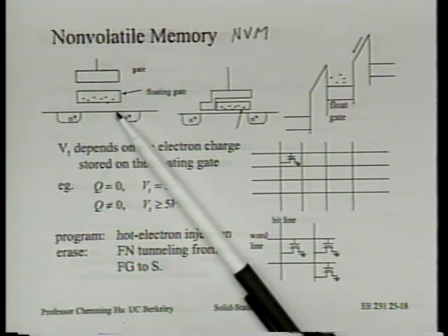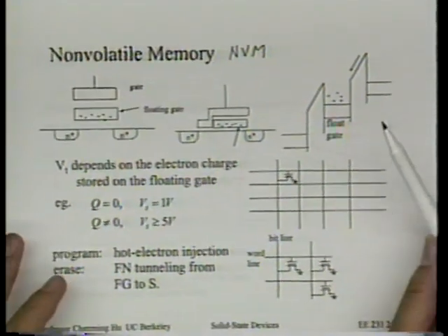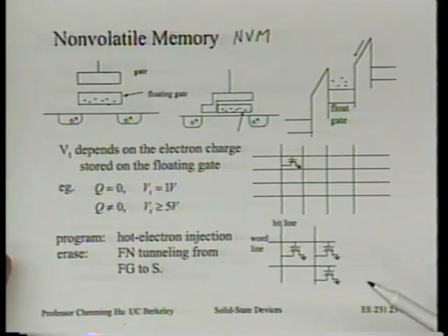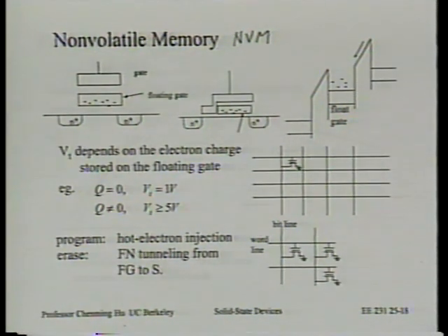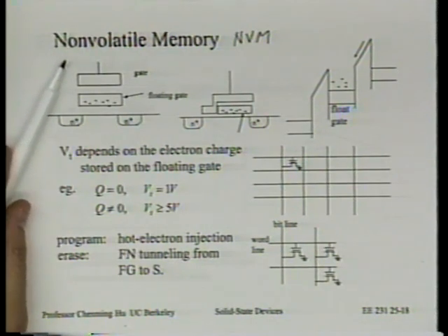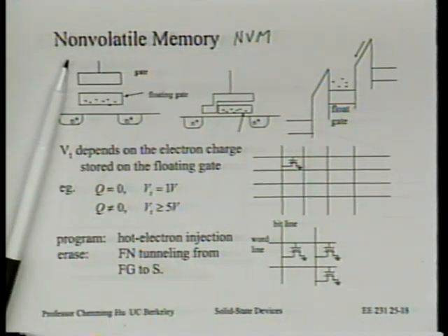I said these are very stable traps because the barrier is very high. Do you know how long these electrons have to stay on these non-volatile memory floating gates? The general expectation is that in order for memory to be called non-volatile memory, it should store data for 10 years. In other words, let's say you unplug your computer for a long time, and 10 years later you plug it in. Well, the basic setup is still on the computer. The BIOS is still available. That's because it's stored in this non-volatile memory. It will still be there.